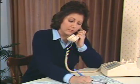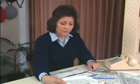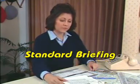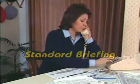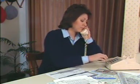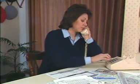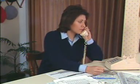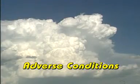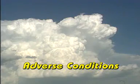As your departure time nears, a standard briefing is necessary to obtain the most complete and in-depth weather data. A standard briefing is comprised of 12 separate and sometimes lengthy elements, so be prepared to write when you call. The briefer normally provides you with the following information: reported and forecast adverse weather conditions, information regarding whether or not VFR is recommended based on the current and forecast weather,